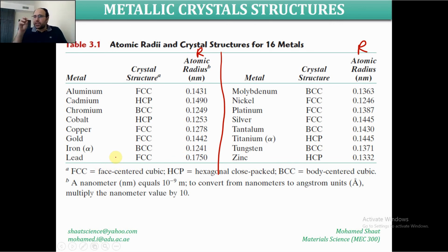So it means that you may have the same material type but with different crystal structures. These two types of the same material with different crystal structures have different properties. As I mentioned, you may have an iron with FCC and another iron type with BCC. These two are still the same element, Fe, in terms of chemistry, but in terms of atomic or crystal structure they are different, and that's why they are different in properties. Also, we may have an aluminum material with an FCC crystal structure and another one with a BCC crystal structure. They are different, and so on.